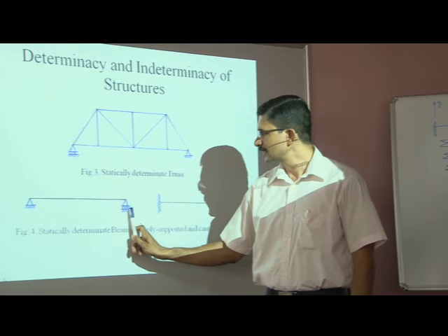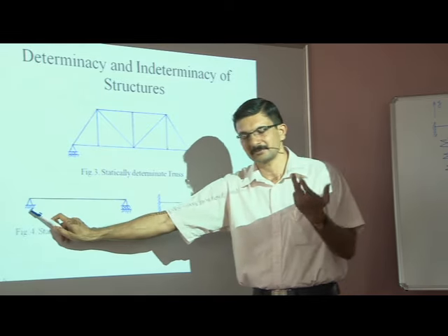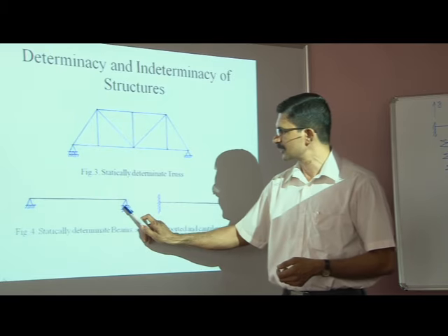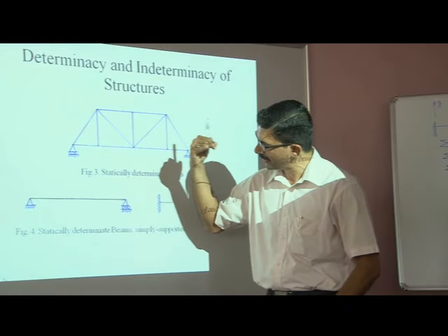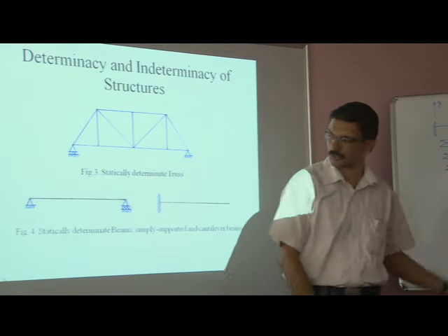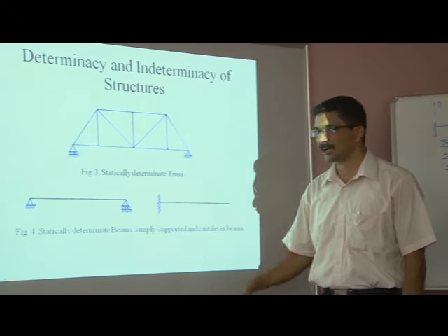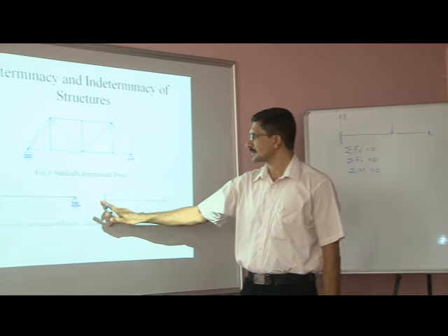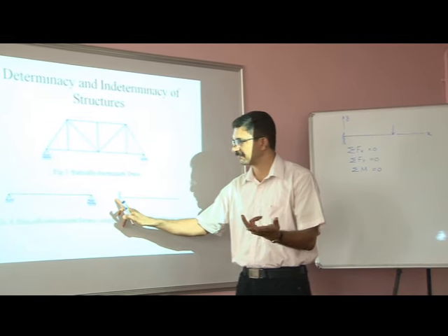So the support reactions, as in this case, will be 3 in number, maximum 3 in number. There we can expect 2 independent reactions, and here we can expect 1 independent reaction. So because of the external loads, we can find out the reactions with the help of the equations of statics alone. So this beam is also statically determinate. This is the cantilever drawn earlier already on the board. Well, the support over here is called a fixed support, and we know what is a fixed support.